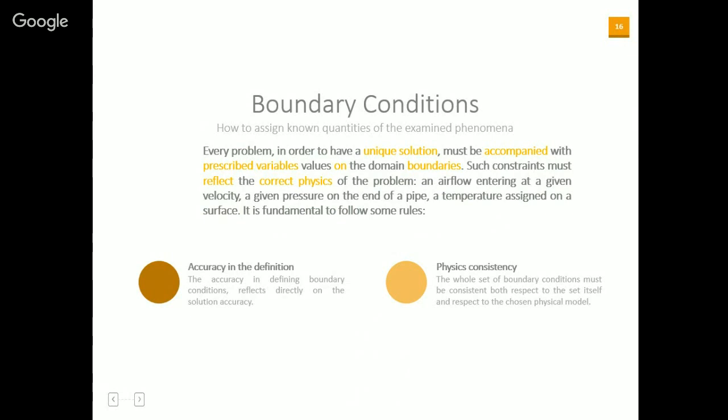If on the inlet you assign a velocity that is going inside your domain, on the outlet you have to define a consistent boundary. It means that if you assign an inlet also on the outlet, let's say a velocity entering your fluid domain, the air cannot exit in any way, so it would be a problem leading to error or an inaccurate solution.